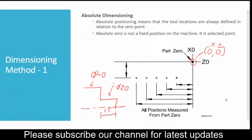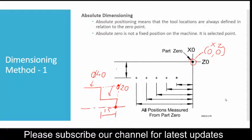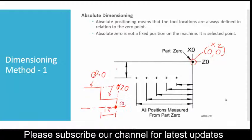Suppose I wanted to indicate this point, then how do I indicate this point with respect to this point? This point for me is 0, 0. In this direction, as I said, lengthwise it is z, and diameter wise this would be x plus, and on this side it is z plus. So we must ensure that we write the x coordinate in diameter and z in length.